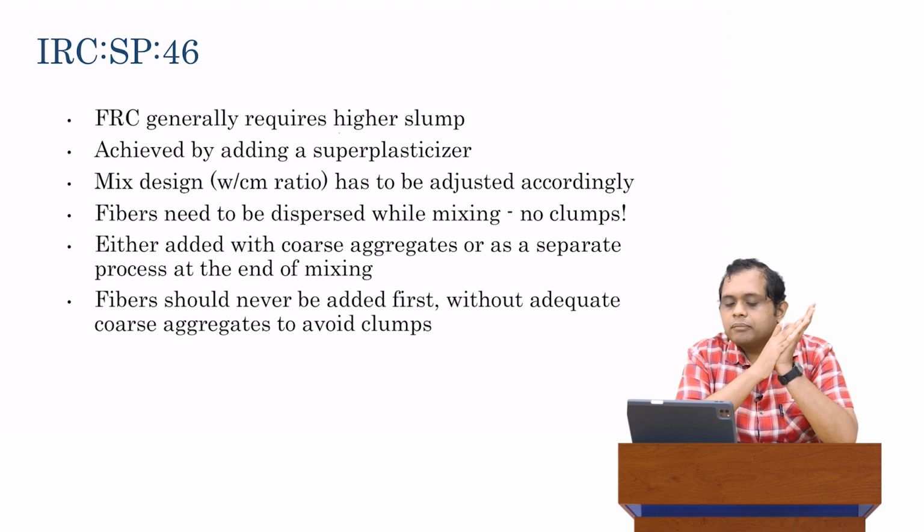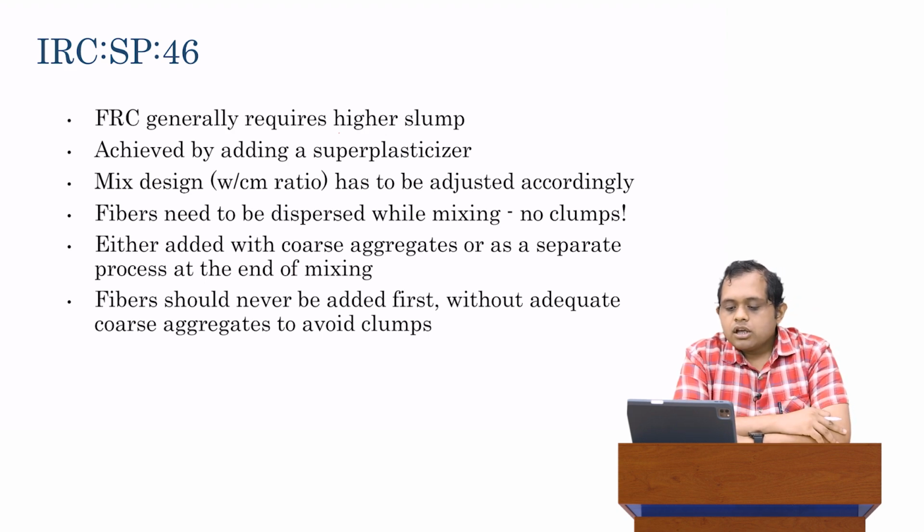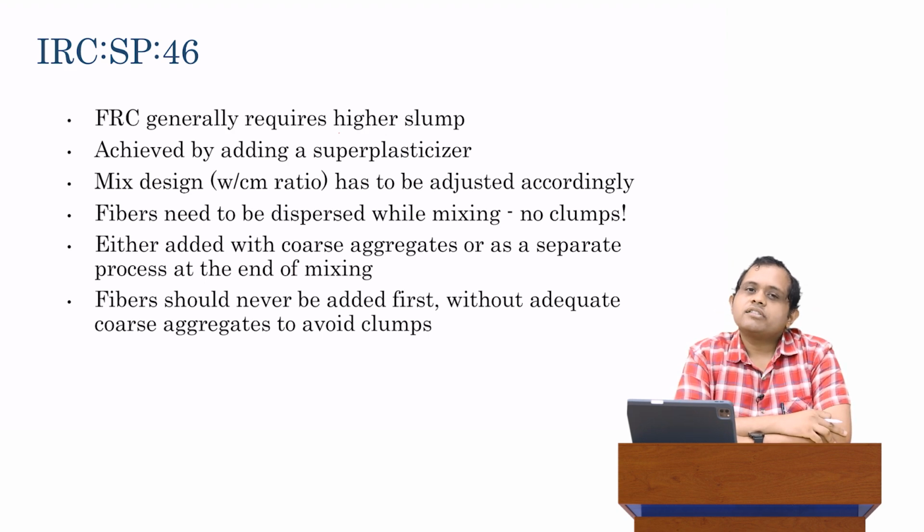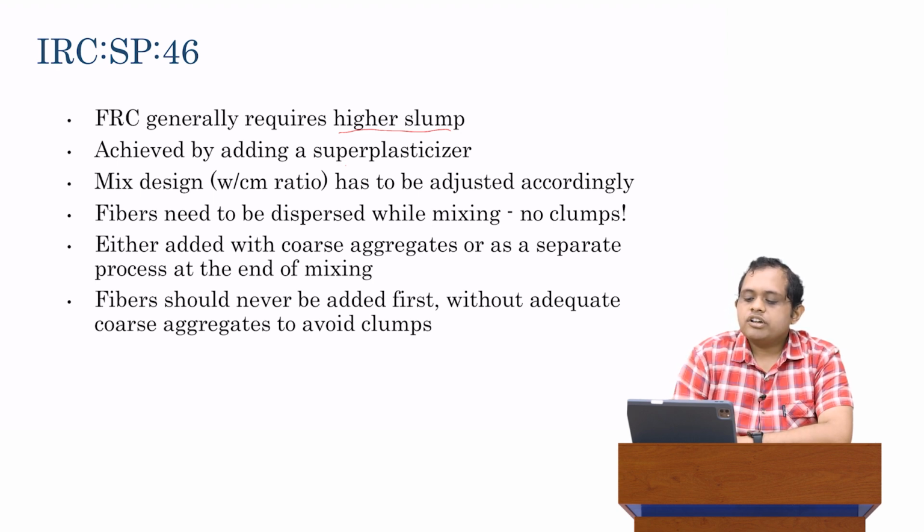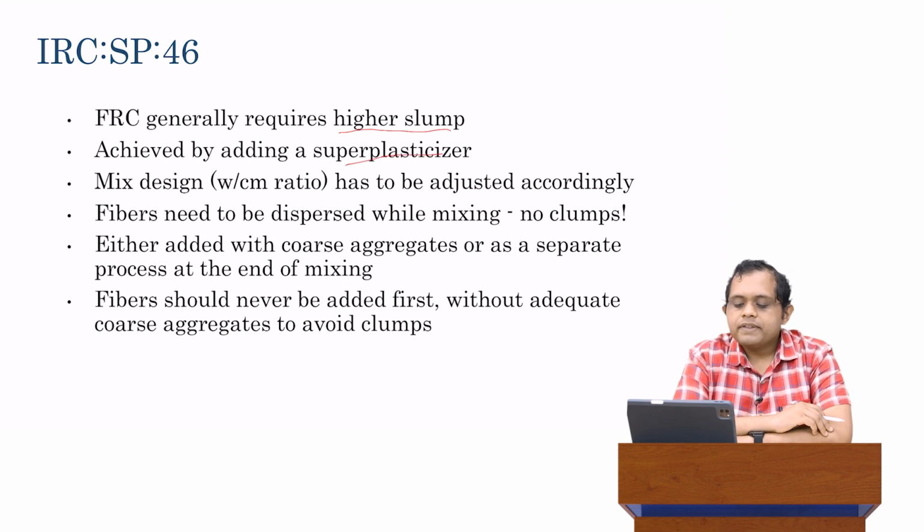Okay, some final thoughts on FRC. FRC generally requires higher slump. That is, when you're mixing fiber reinforced concrete, you don't do the mix design identical to conventional concrete. Generally, you do require some amount of higher slump. You don't add water to that because you're going to decrease strength. So it does involve adding some superplasticizer. The mix design, therefore, has to be adjusted accordingly.